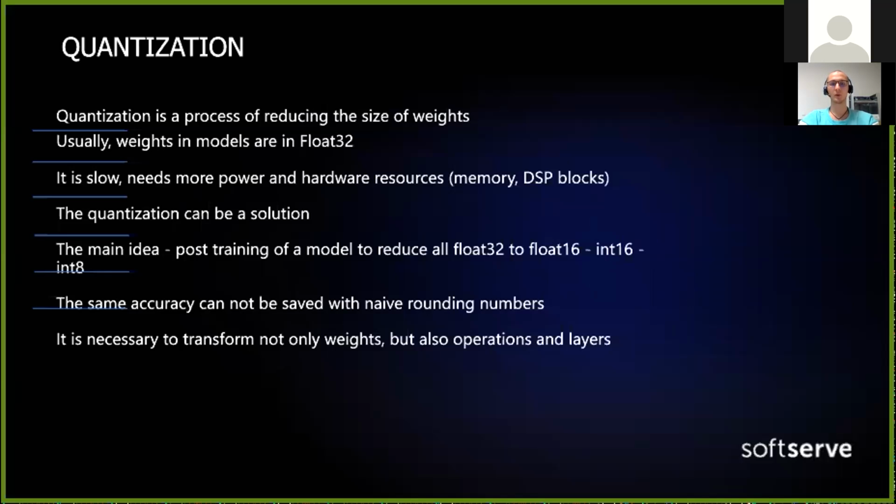It is also post-training, and for each model, for PyTorch, TensorFlow and Caffe models, the process and input data will be different, but the result is a quantized model that you can compile and deploy on the FPGA.